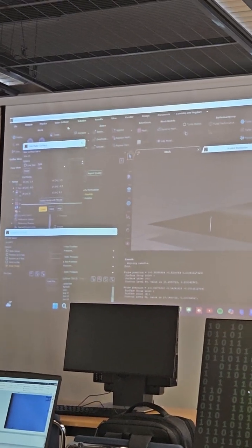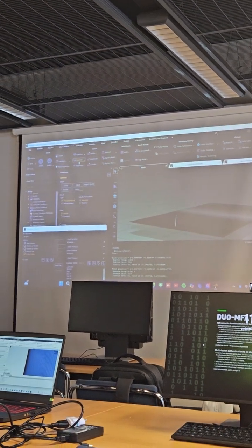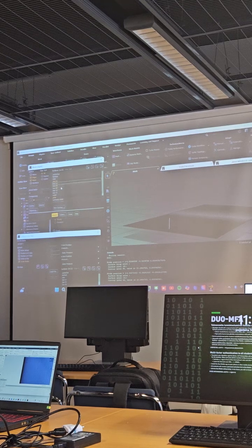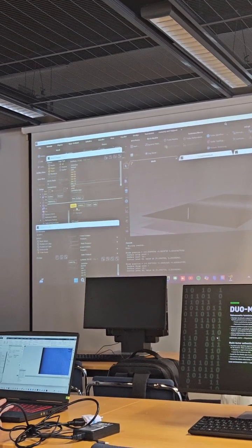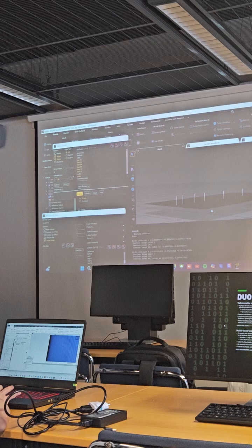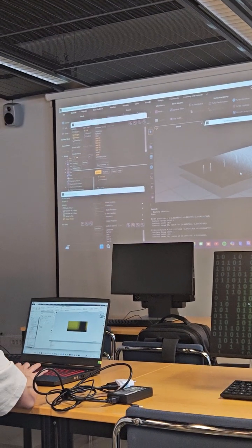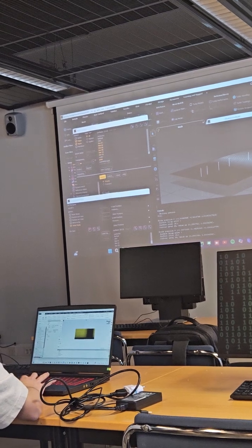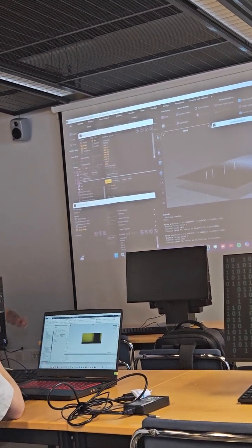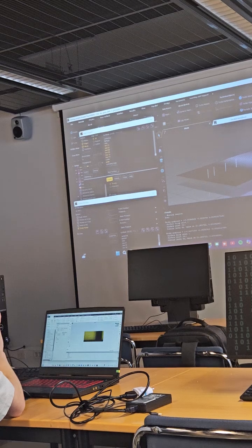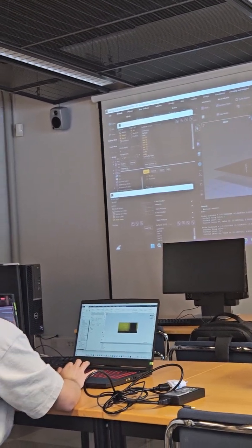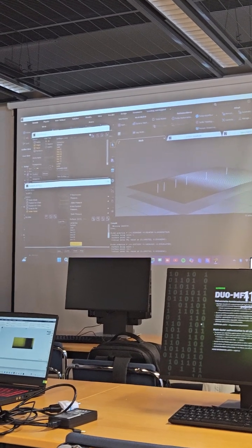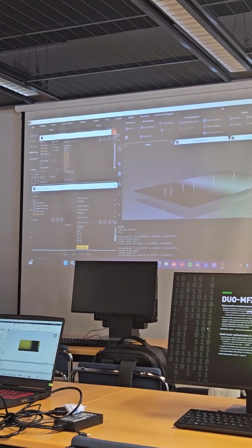Once I've done that, I can close this window. Again in display, I can plot all of these lines to check that they are correct. So I'm covering our domain, our plate, with good resolution. Now we need to plot the flow quantities over these lines. Okay, so I can close this mesh display.